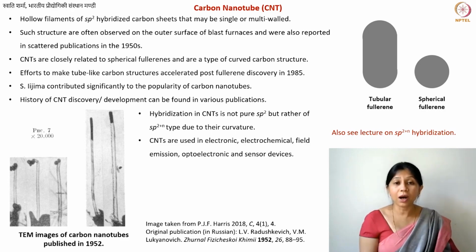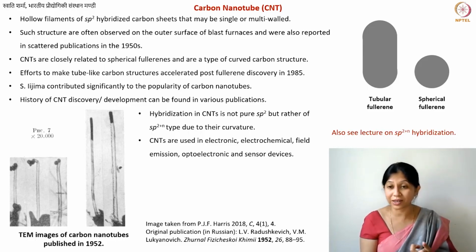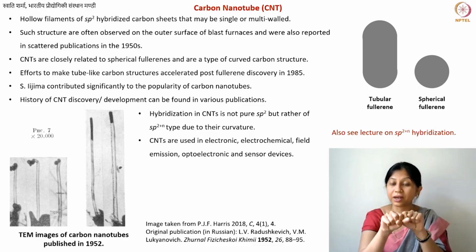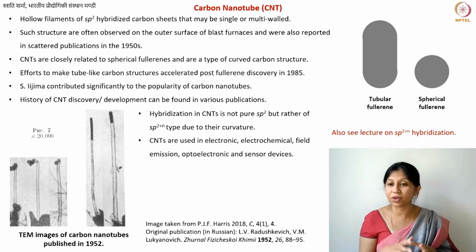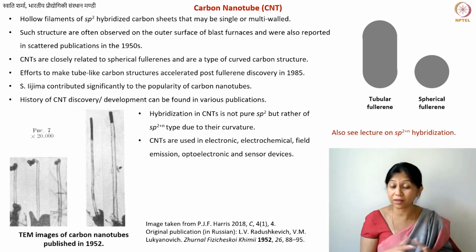Okay, so the applications of carbon nanotubes. Again, I will not go into the details because there are so many applications of this material. What you need to understand is that we already know the electronic properties of this material are interesting. It can be conducting or semiconducting, and if you join one conductor and one semiconductor, you can get single-element conductor-semiconductor junctions. There are so many things you can do with it. Already there are a lot of electronic applications, especially field effect transistors, where carbon nanotubes are used a lot. Various types of sensors can also be made using carbon nanotubes.